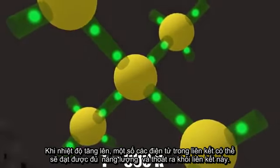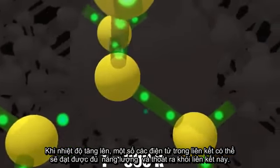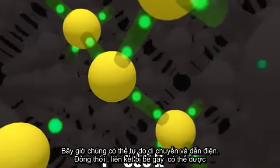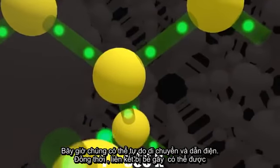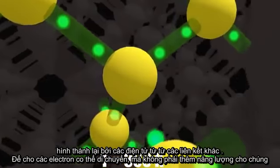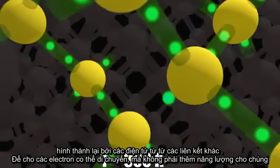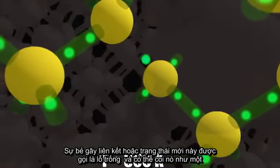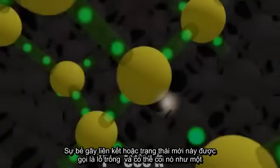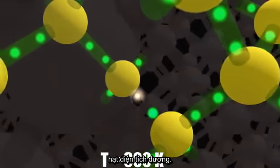When the temperature rises, some of the electrons in the bonds are able to gain thermal energy and escape. They are now free to move and to conduct electricity. At the same time, the broken bonds can be occupied by electrons from other bonds. For these electrons to move, no additional energy is required on average. This broken bond, or new state, is termed a hole, and behaves as a particle of positive charge and mass.